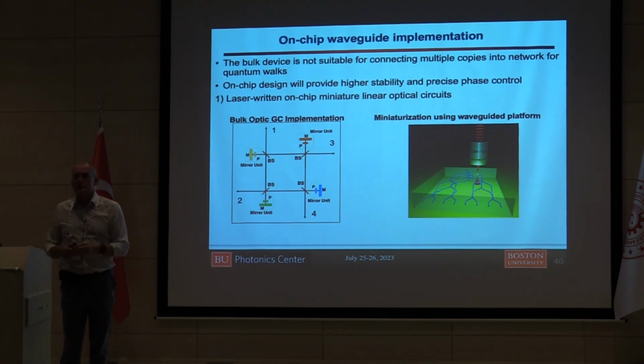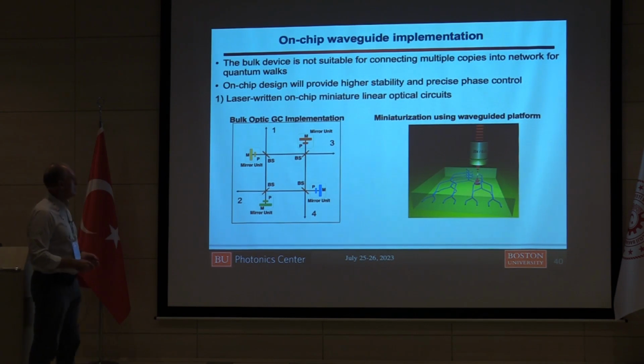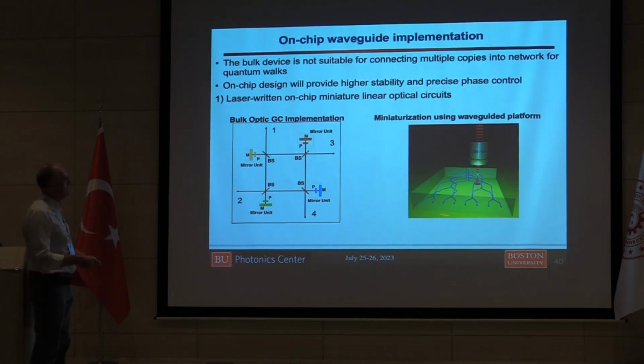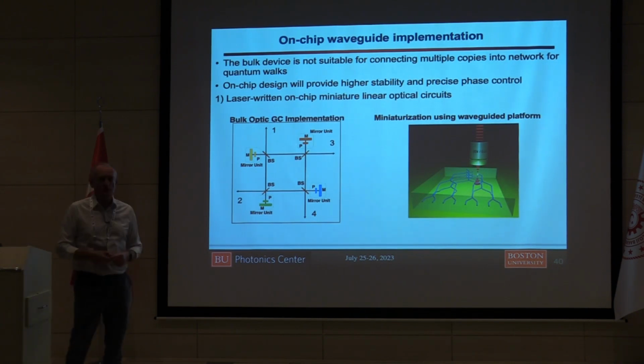And then the question was how to do that. Because all quantum optics miniaturization today goes through this principle. We have a beam splitter, so it will be coupled waveguides. You have a mirror, it will be a distributed Bragg mirror in there. A phase shift is just an electrode next to the waveguide. That would be your phase shift. If you try to do this, it's still pretty big and very, very difficult to do.